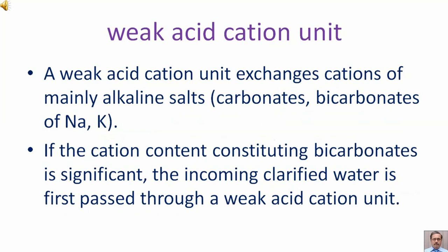A weak acid cation unit exchanges cations of mainly alkaline salts, that is, carbonates, bicarbonates of sodium and potassium. If the cation content constituting bicarbonates is significant, the incoming clarified water is first passed through a weak acid cation unit.